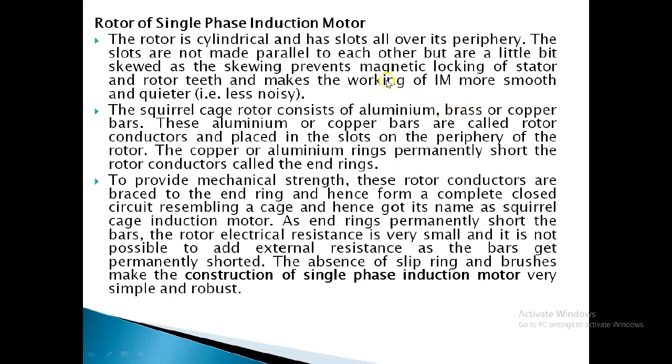Then come to the rotor construction. The rotor construction of a single phase induction motor is very similar to the squirrel cage 3-phase induction motor. I will review the three-phase induction motor rotor construction here, and tell you some points. The first point is that the rotor is cylindrical and slotted all over its periphery, as you saw in the previous diagram.